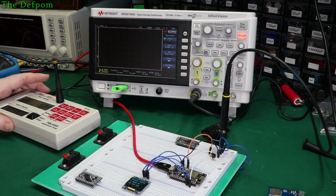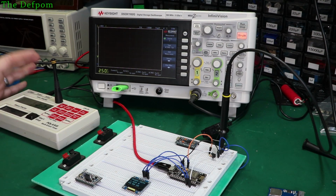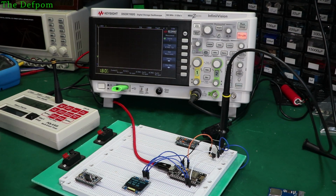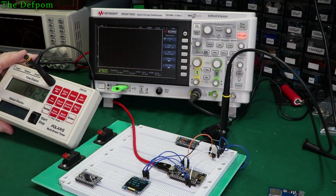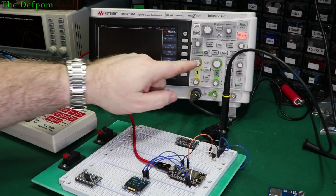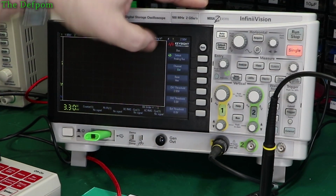Because of that, it's actually a bit tricky to deal with, because it's got different functions, and depending on what those settings are, it can influence the decoding system. It was by default 1200 baud. I've changed it now to 4800 baud just because I want the data to come through a little bit faster. It can actually get higher than that if this is used for other functions as well. So maybe they're running a cable out to a display, maybe they need a bit more noise immunity, that sort of thing. Having a higher baud rate can cause problems with that, so that's probably why it's defaulted to a very low baud rate.